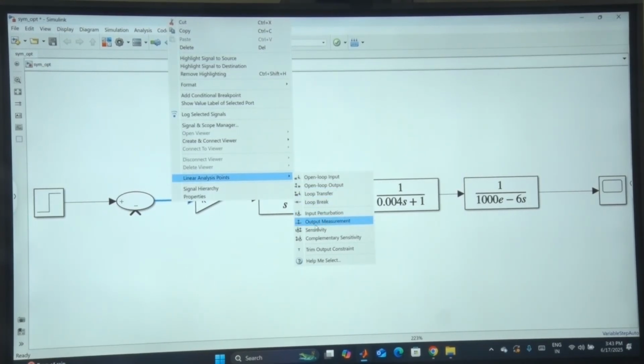So like that, let's say that we write x dot equal to Ax plus Bu, and then y equal to Cx. So y is what? Y is your output, right? And if we have a step input somewhere, we can give an input perturbation. So depending on what this signal is in your model, you can define it as the input perturbation, or you can define it as your open loop input, or if it is output, you can define it as output.